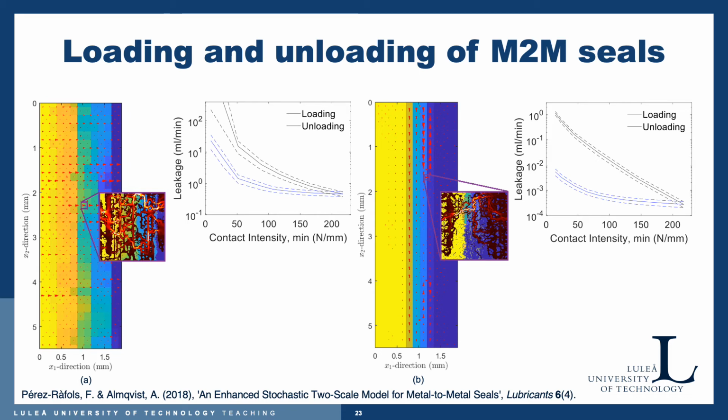In this case, the leakage is much more meandering, and it just loops over these ridges, which are actually turning grooves. So it can just jump over the turning grooves at certain places where we have large pressure drops, and then the leakage on the micro scale looks like this.